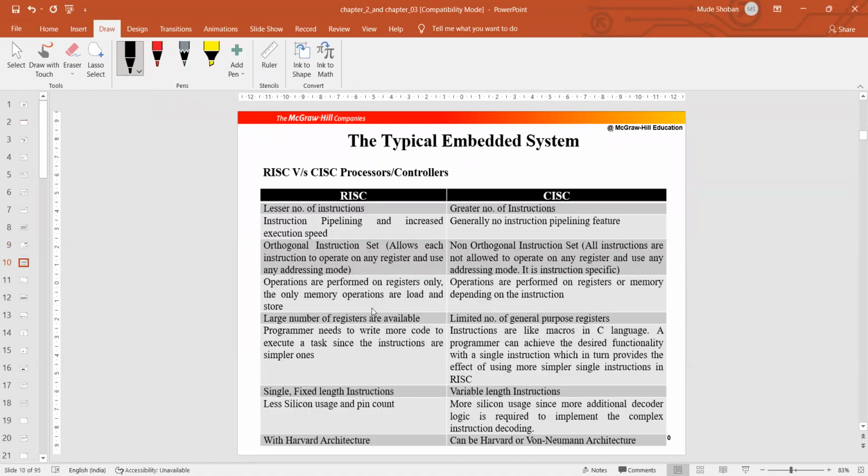And this is the RISC and CISC, a very important comparison. Reduced instruction set computer and complex instruction set computer. So earlier we have noticed this. So the preferable architecture for the processor. See, generally RISC and CISC, it is not the architecture. I can say RISC and CISC is not the architecture of the processor. The architecture of the processor depends on the Harvard architecture and Princeton architecture.